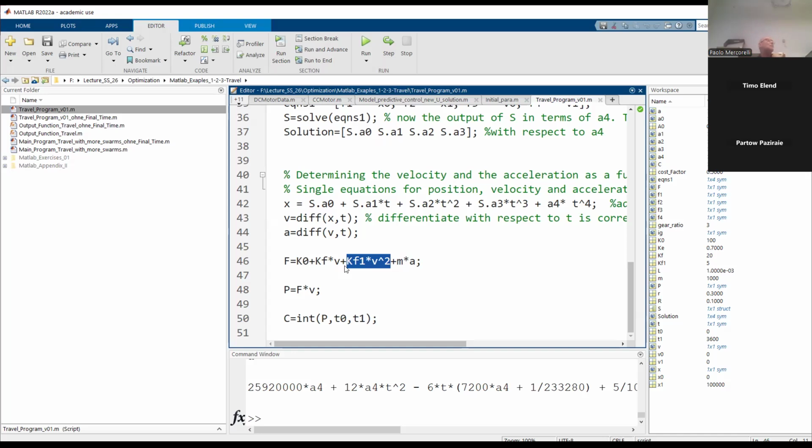The velocity is always positive. Always positive means always one direction. Otherwise, I think I told you about this concept. No? That the model of the friction force related to the even function must be multiplied by SGN, because the friction physically is an odd function, in order to be sensitive with respect to the direction. But anyway, the same direction.